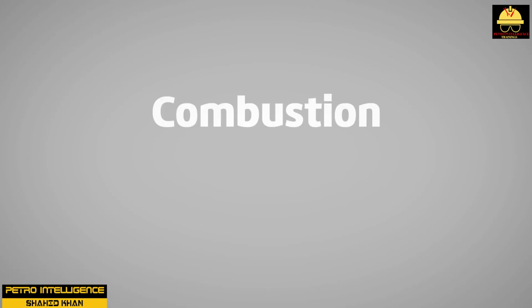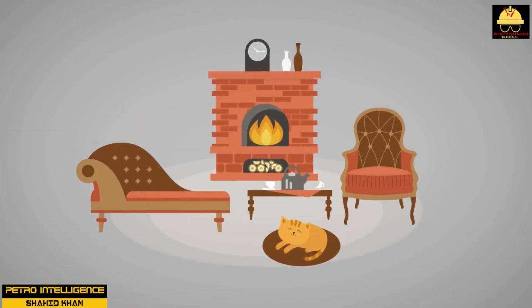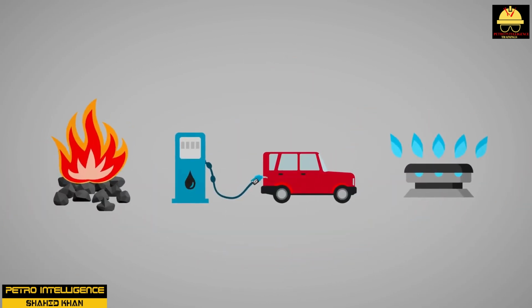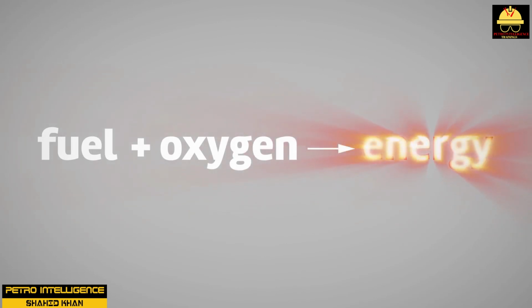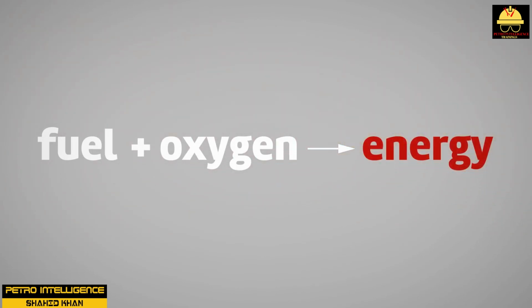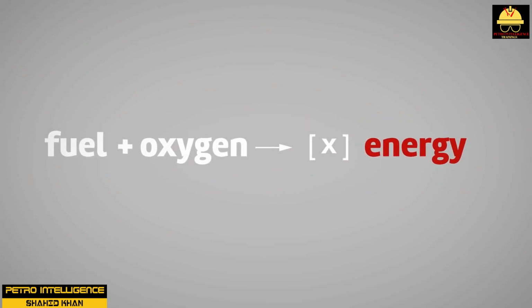Combustion. Combustion is a rapid chemical reaction that occurs when proper amounts of fuel and oxygen, O2, come into contact with an ignition source and release heat and light. Furnaces use this principle to provide heat. Complete combustion occurs when reactants are ignited in the correct proportions. Incomplete combustion occurs in a fired furnace when not enough oxygen exists to completely convert all of the fuel to water and carbon dioxide. Many furnaces use natural gas or methane, CH4, as fuel for the burners.